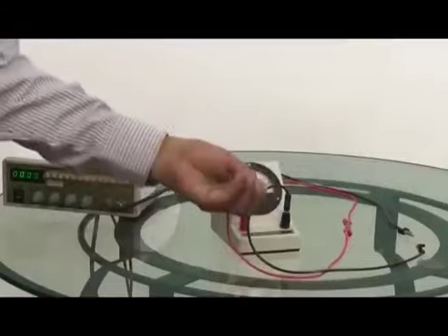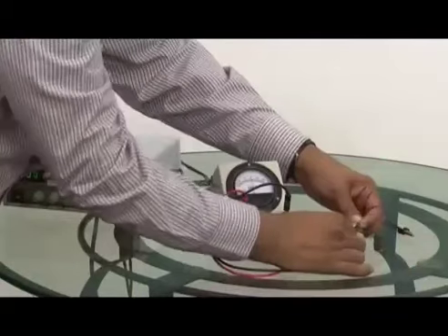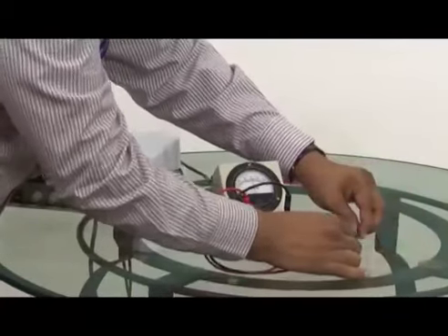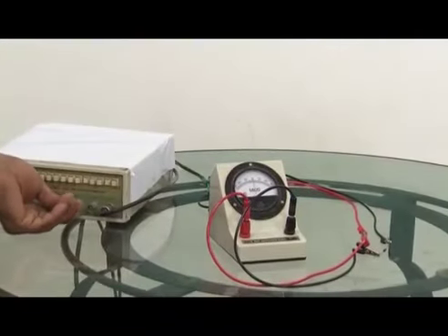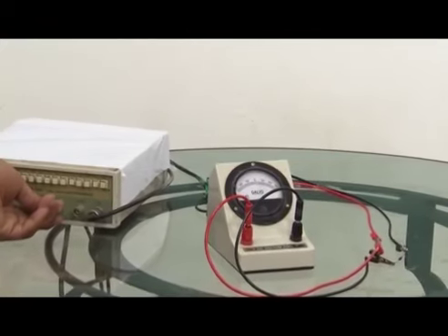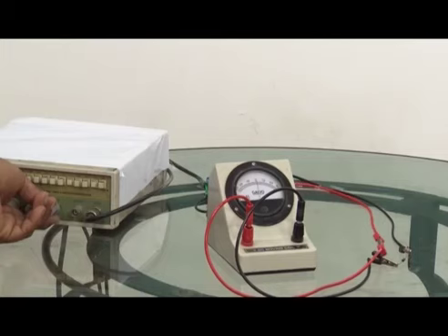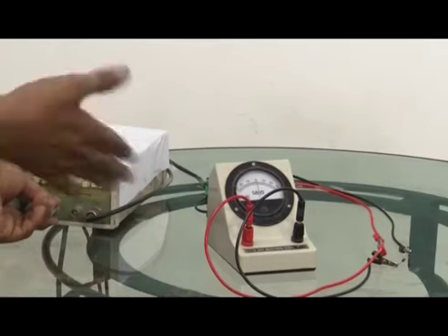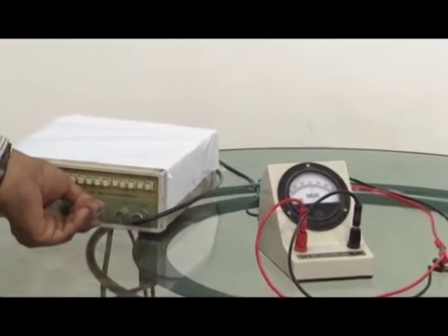So, once again the same diode which I had used, I have connected in this circuit in between, right, and see what happens when I give the amplitude. It only goes in the right direction and then stops here. It goes in the right direction and stops. It is not going in the left direction. Half the time there is a current, half the time current is 0, but the current is only in one direction. So, that is the rectifier action that we had discussed.